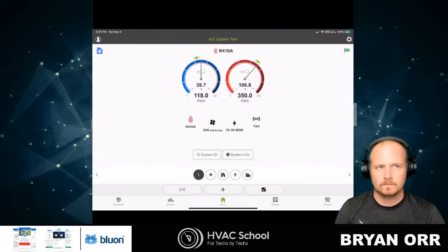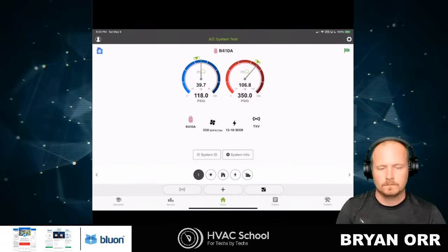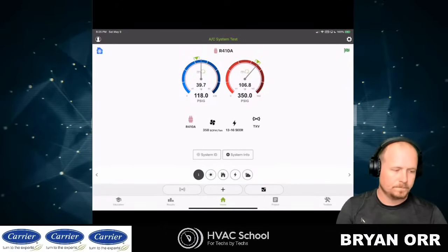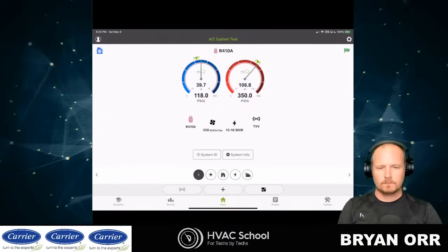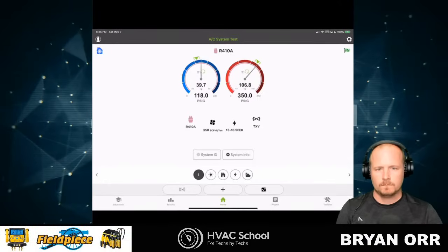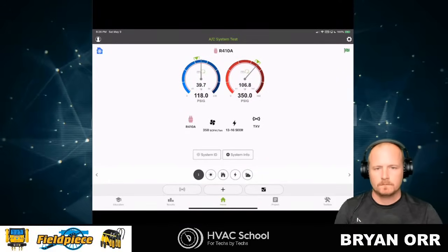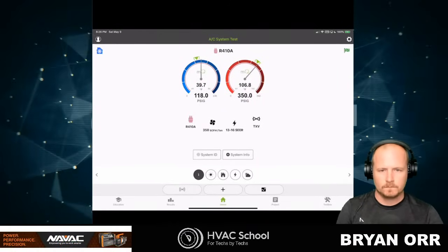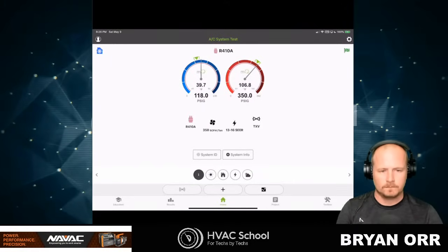And then what we're really watching at that point is to make sure that the suction gas stays below 65 degrees, so we get adequate compressor cooling, right? Just because you do a benchmark doesn't mean that all the variables are going to lock in. We lock in airflow, static pressure, pressures, the superheat and the subcooling, but there are a lot of things that are a function of the load too, and those things will change with the load, indoor and outdoor.